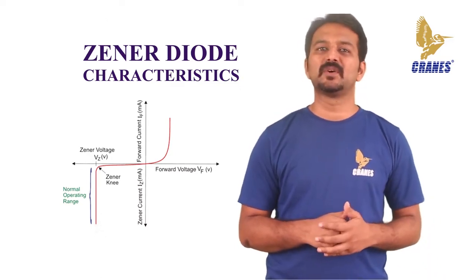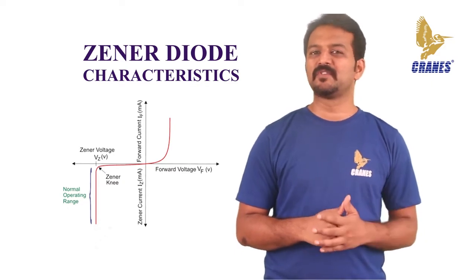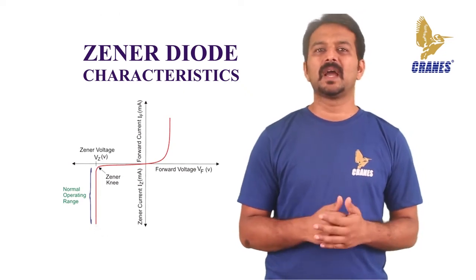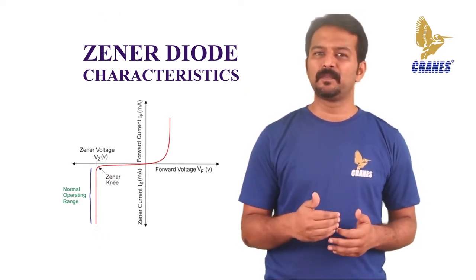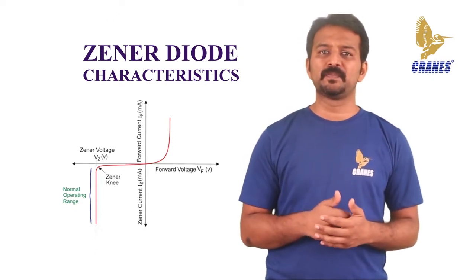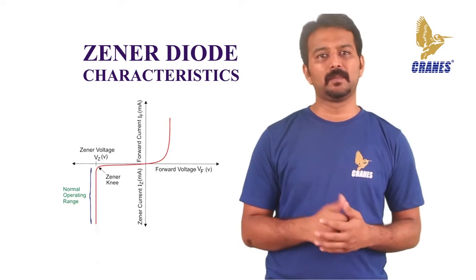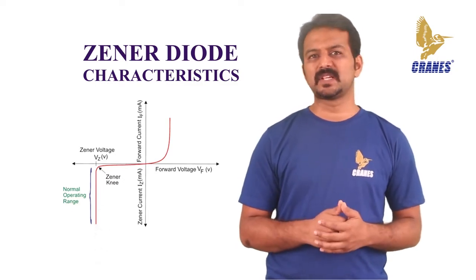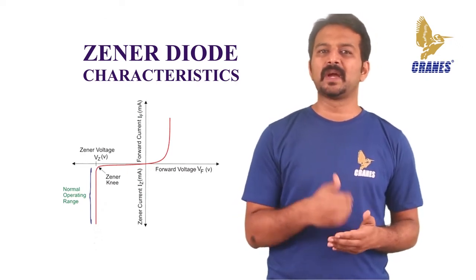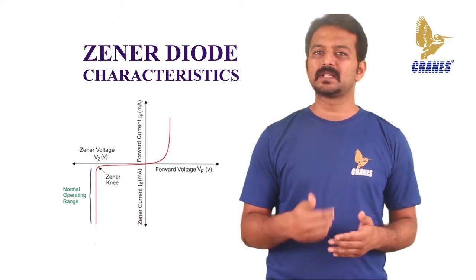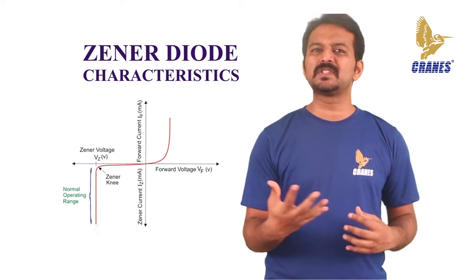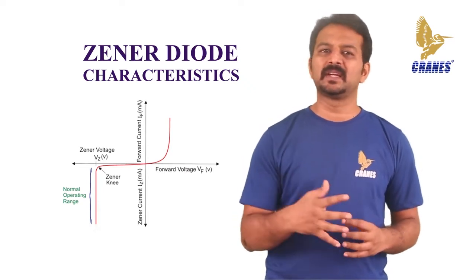However, the Zener diode, or the breakdown diode as it is sometimes referred to, is basically the same as the standard PN junction diode, but it is specially designed to have a low and specified reverse breakdown voltage, which takes advantage of any reverse voltage applied to it. The Zener diode behaves just like a normal general purpose diode consisting of a silicon PN junction when biased in a forward direction, that is, anode is positive with respect to its cathode. It behaves just like a normal signal diode passing the rated current.